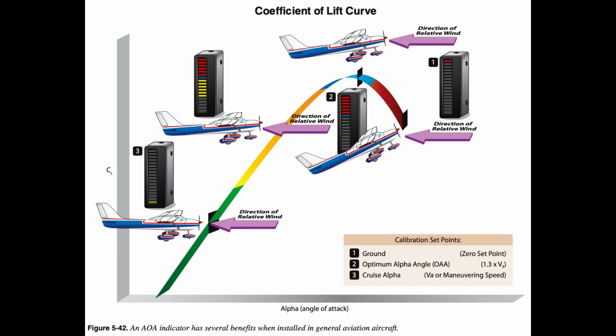Installation of AOA indicators not required by type certification in general aviation airplanes has recently been streamlined by the FAA. The FAA established policy in February 2014 pertaining to non-required AOA systems and how they may be installed as a minor alteration, depending upon their installation requirements and operational utilization, and the procedures to take for certification of these installations. For updated information, reference the FAA website at